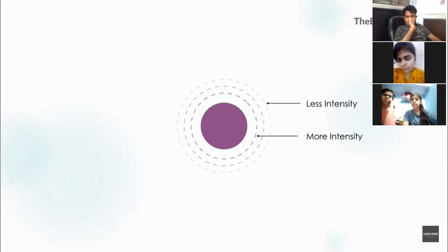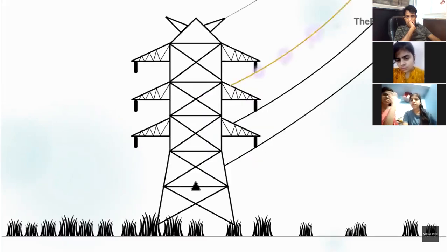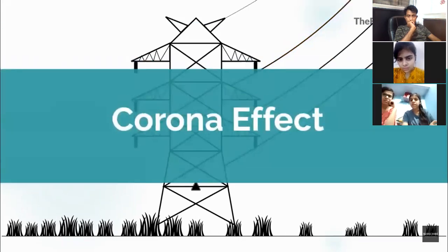If the electric intensity is high enough, because of the breakdown of air, a faint violet glow will appear. And at the same time, a humming noise will be heard. And this is nothing but the corona in electrical engineering. If the electric field intensity increases, the glow and the noise will also increase until a spark takes place. Further, if the surface of conductor is not smooth and it has some rough points, there the glow will be brighter as compared to the smooth areas.